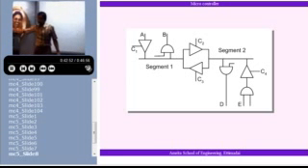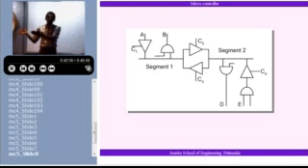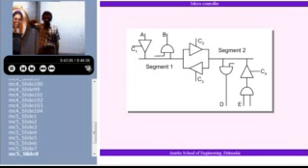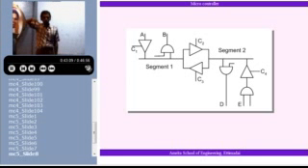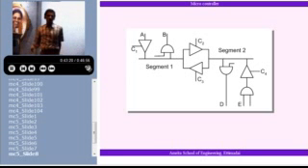Now look at the things we have discussed. I have an accumulator here, I have an ALU somewhere, another accumulator, a register. I can pick data from any register through a tri-state buffer. I put lines all over the place. I connect data to a data line, enabling a tri-state buffer from a register, bring it to an accumulator, do something, and take it to another register. It's up to us to do all this. Is it okay?